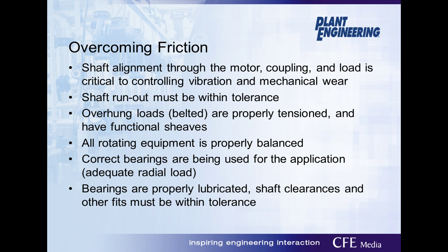And then thinking about even vertical motors, consider whether you have axial force that is upward, downward, or balanced both ways to determine if you may need a thrust bearing on one end of the motor, and that would be most commonly matched with a guide bearing on the other end.